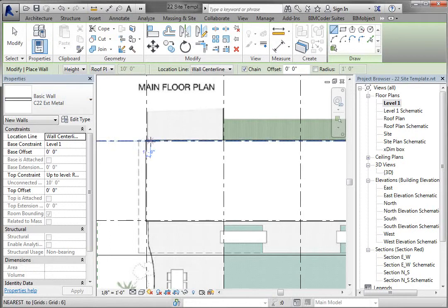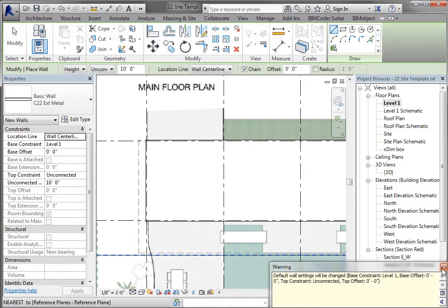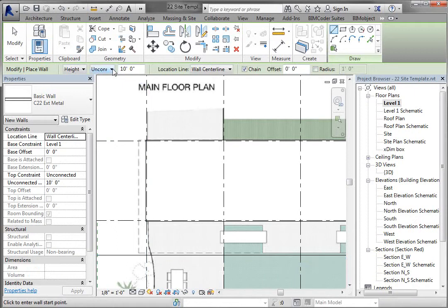Now basically all we have to do is use a line. Here's the height, it's going to do it by height. Its height, we want it to go to the top of the column. So this is top of column. This is a level that exists here, so I'm going to pick top of column.